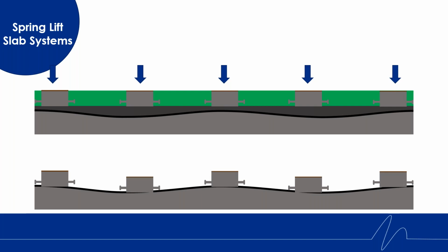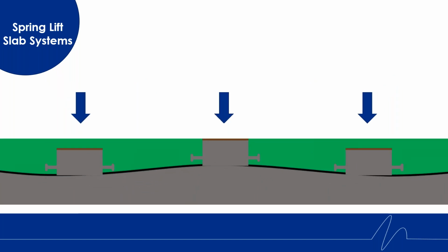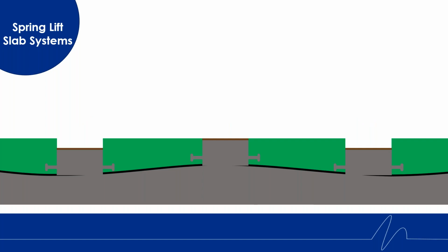In the second example, we see what happens when the structural floor was not corrected. Yes, the top of the concrete is flat. However, the two isolators that can be seen are buried with no access and will support more weight. In this instance, access to the cans needs to be chiseled out of the poured concrete.